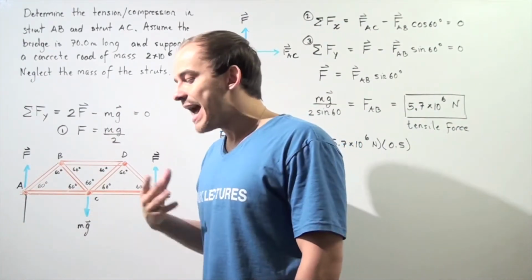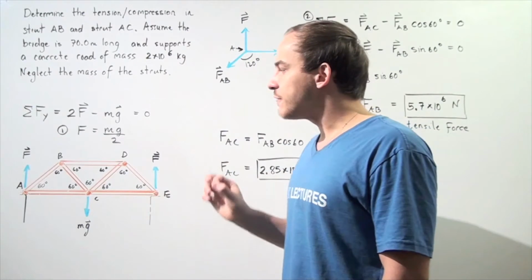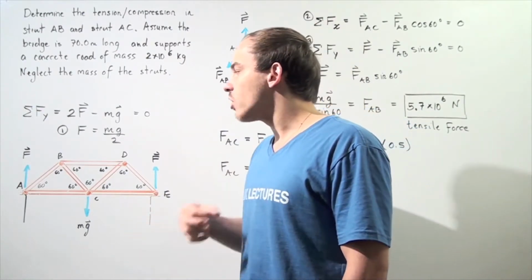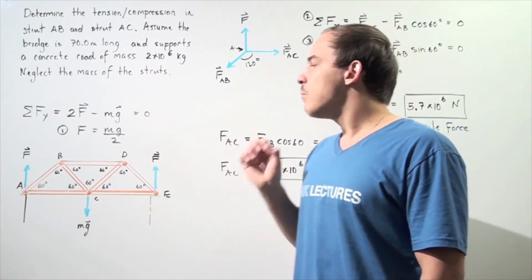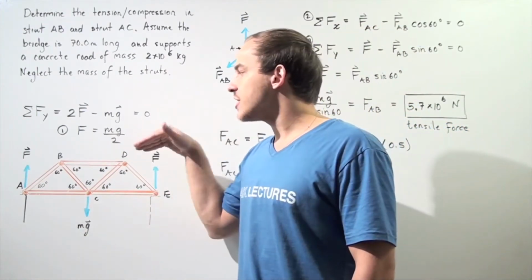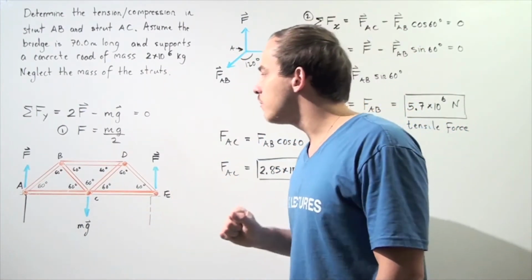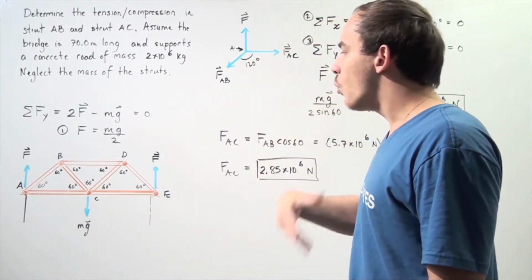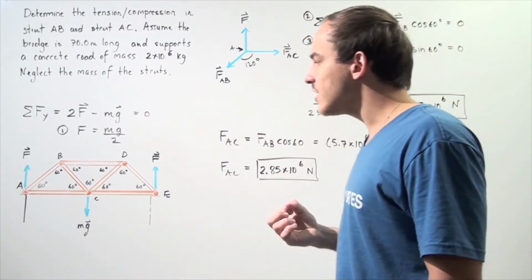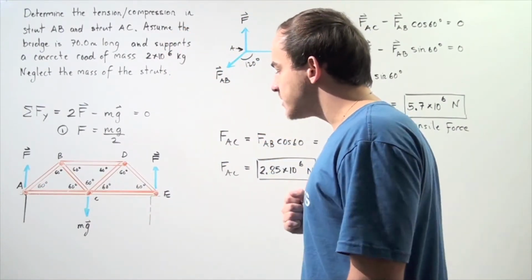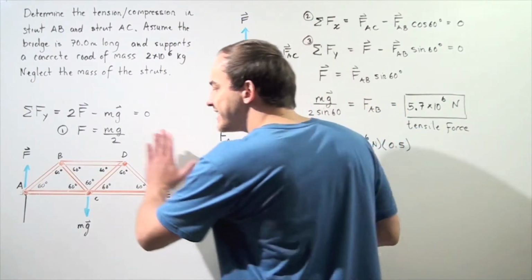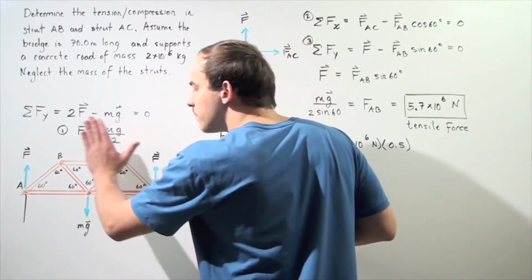So that will allow us to assume that the forces, the tensile or compressive forces that exist in any one of the struts, point along the length of that strut. And that will become important in just a moment when we're describing the force diagram at point A. Now, before we go into that, notice we're only examining the side view of the bridge.